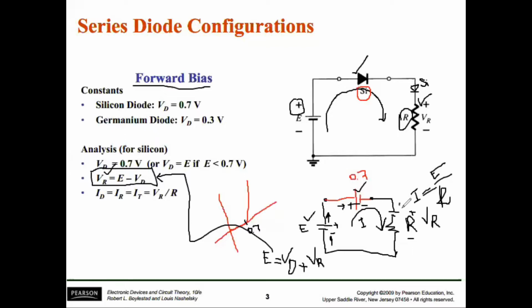This voltage source will have a value of 0.7 because we are using a silicon diode here. So if this is the scenario, we will analyze it accordingly. In this way, the diode configuration will be used to find the current and many other things.